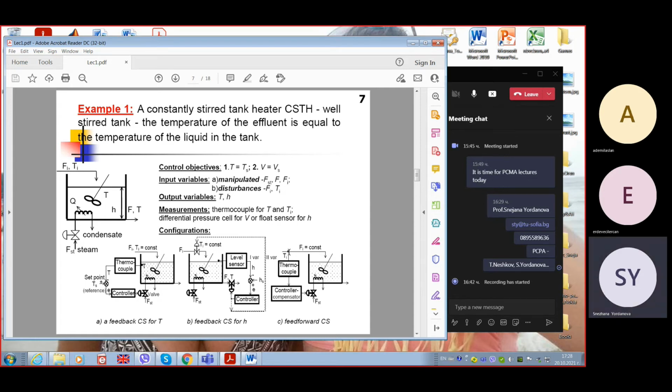So, measuring the disturbance, we act with advanced compensation. Before this liquid with cold temperature enters, we have already increased the heating agent, so the inside temperature will not be influenced by this disturbance. But this is called a feed-forward advanced compensator in open loop of disturbance.